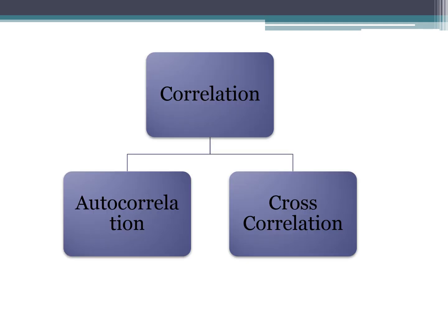So when we want to compare two signals, or compare how one function is like another function, correlation basically provides a quantitative way of comparing two functions. For example, when you are given an EEG signal and you want to find the presence of alpha rhythm in it, what will you do? You will cross correlate your signal with the signal having an alpha rhythm. So by cross correlation, you can easily find the presence of alpha rhythm in the given EEG signal.